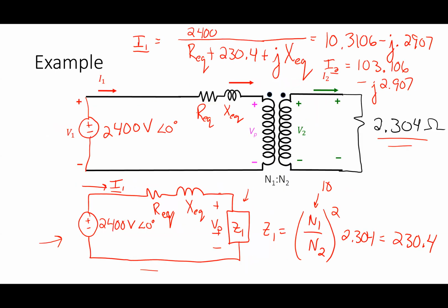In my mind, I always think of it that way. One thing I always look at is in the traditional way of operating a power system, this voltage closer to the load is always going to be lower than that voltage. All right. Because I know that there's always some impedances to the network, which makes the voltages reduce if current flows through it. All right. So I don't know. My brain thinks of it that way. All right. Questions about that?